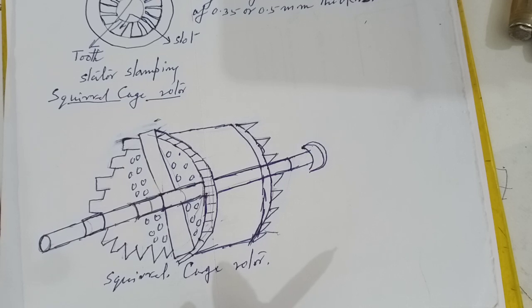Induction motor differs from DC machine in the following ways. Air gap is comparatively much smaller. Absent commutator. Practically a constant speed motor. Laminated stator.